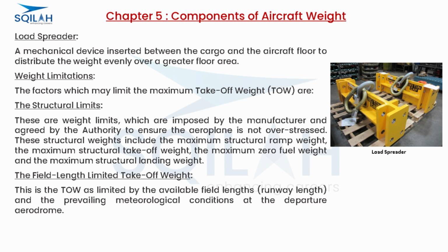Weight limitations. The factors which may limit the maximum takeoff weight, TOW, are the structural limits. These are weight limits, which are imposed by the manufacturer and agreed by the authority to ensure the airplane is not overstressed. These structural weights include the maximum structural ramp weight, the maximum structural takeoff weight, the maximum zero fuel weight, and the maximum structural landing weight.